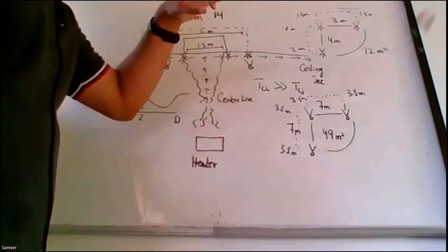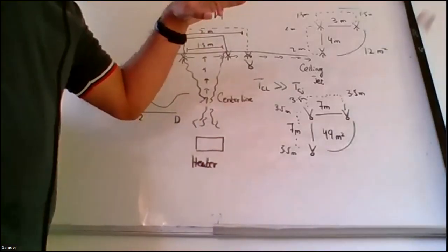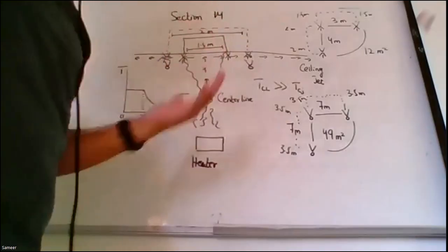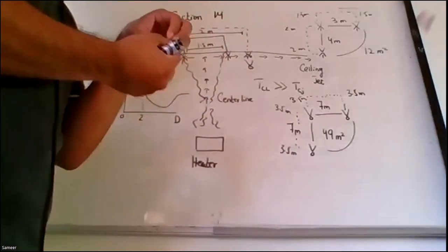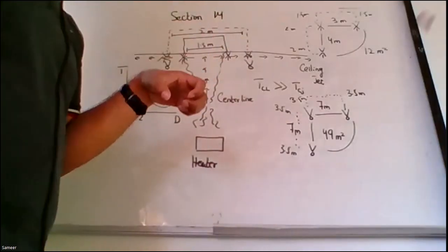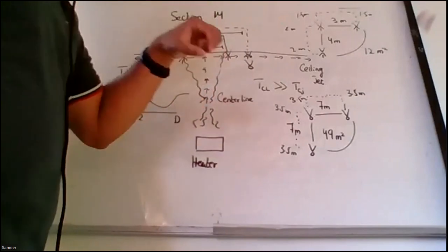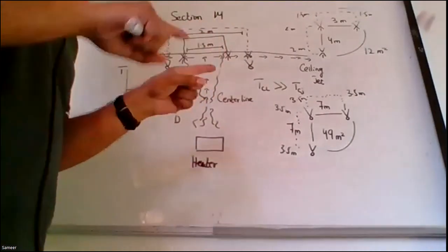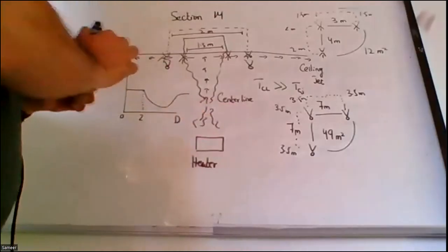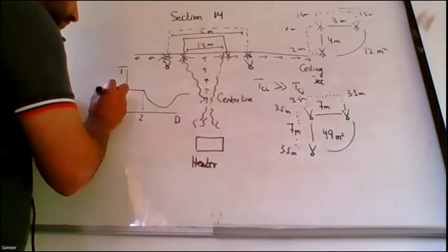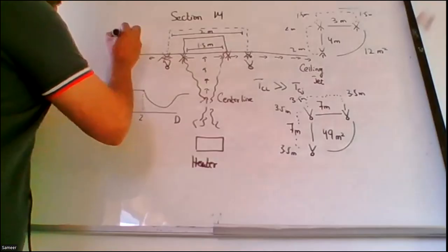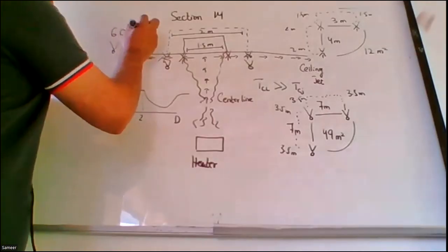If the outside temperature is 32, the temperature at the collection point will be far greater. It may be 65 degrees Celsius because it's continuously concentrating and collecting heat at one point. So there is a temperature differential between the surrounding temperature and the temperature at the heat detector, a vast difference.